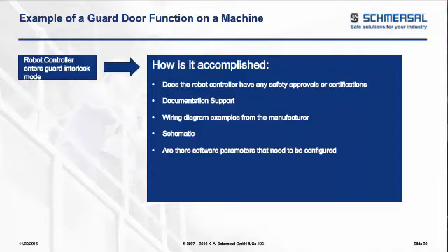But when we're talking machine safeguarding, we're not concerned when things are working. We're concerned when faults occur and what happens. Because we don't want to get in the situation where we open up the door, we break an enabling input, but for some reason that enabling input does not work, and the robot all of a sudden takes off, and then ultimately creates a hazard and potentially somebody getting hurt as a result.